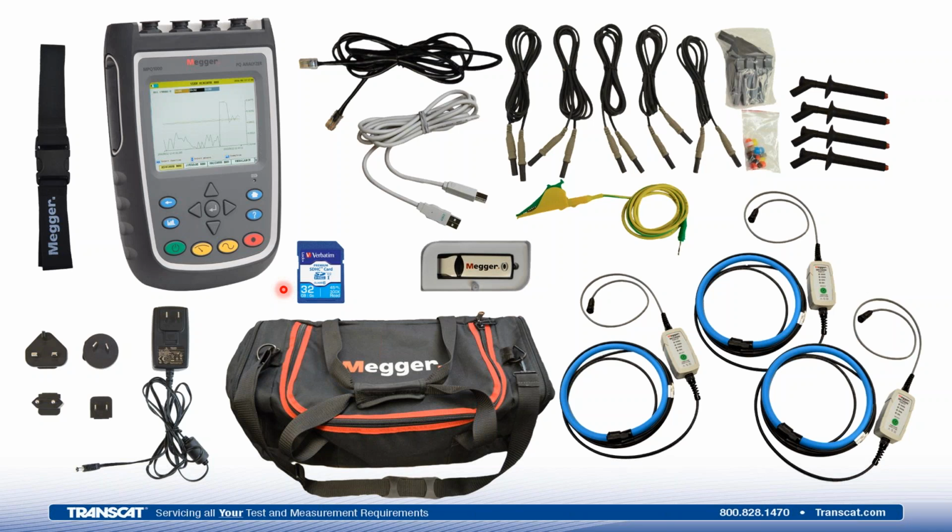So this is what a good power quality analyzer package should include. Of course, your power quality analyzer, your CTs. I would suggest getting an analyzer that uses smart CTs so that it'll tell you if you connected improperly before you leave. That way you ensure that you get the correct data the first time.